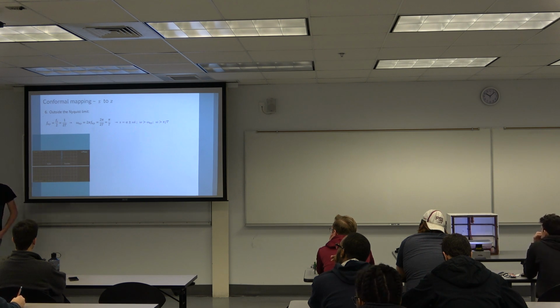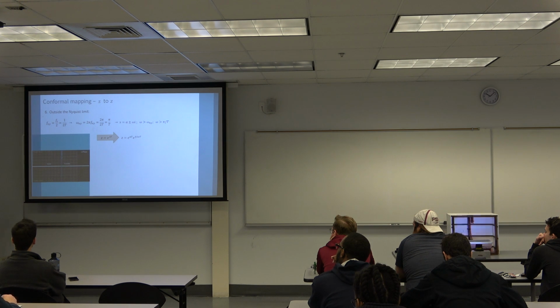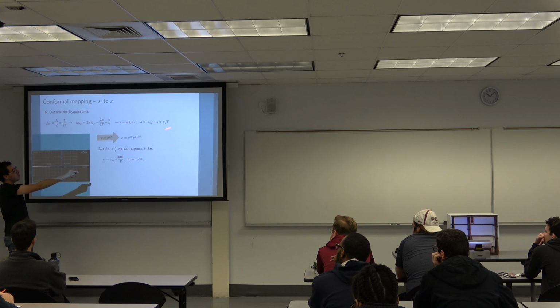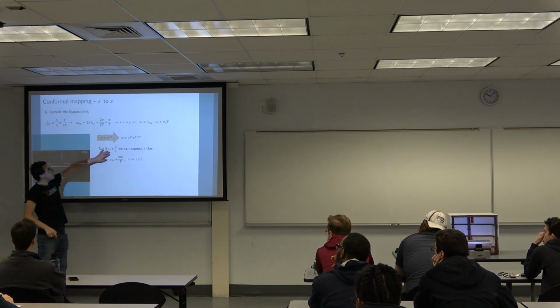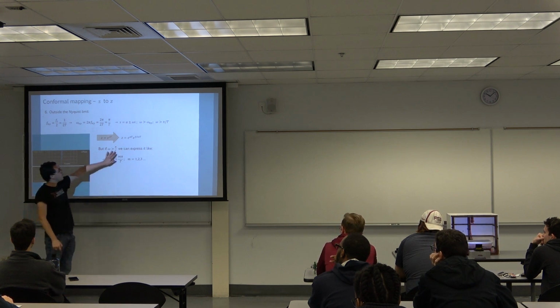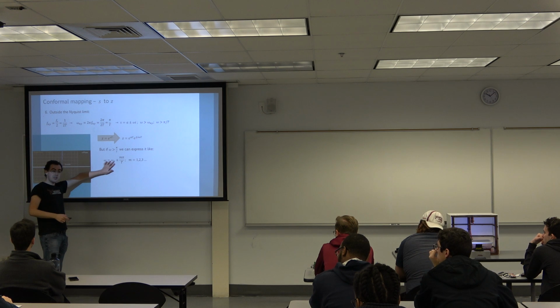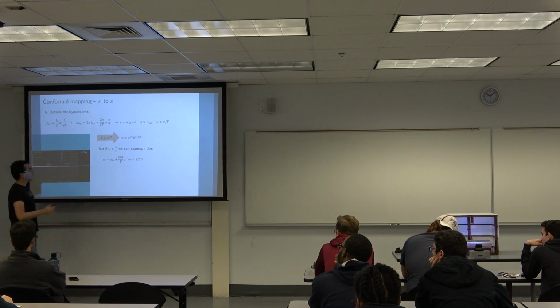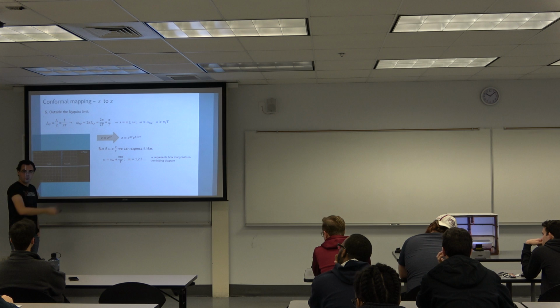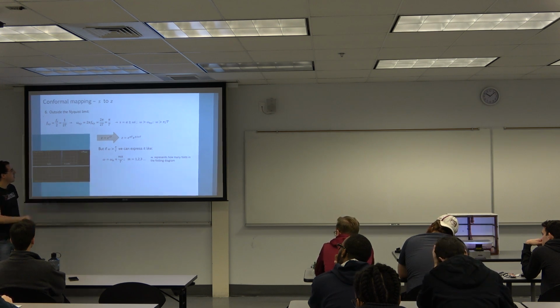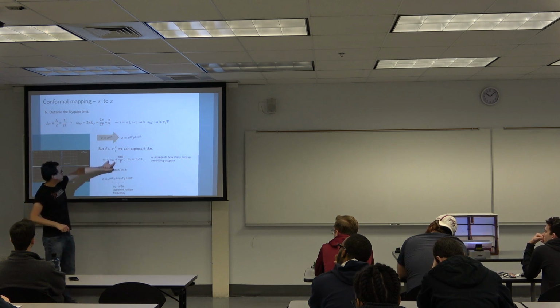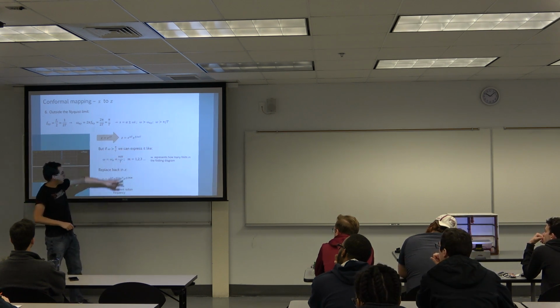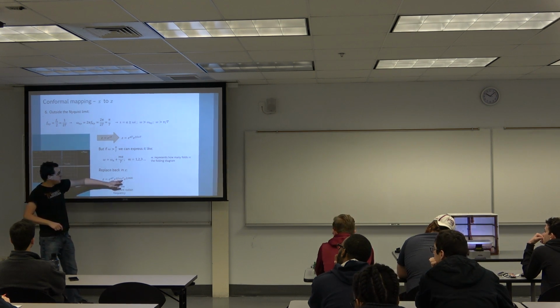where omega is always greater than the Nyquist frequency. And in this case, the Nyquist frequency is pi over T, so this means that omega is always greater than pi over T. If we do that, and we apply the Z transform, then we get e to the i omega T, but omega is always greater than pi over T. So because it's greater than pi over T, I can express it as some apparent frequency omega a, which is less than pi over T, plus some integer number m times pi over T. And m here represents how many folds I have in the folding diagram. So if I do that, I'm just separating the exponential, e to the i omega T, so I get e to the plus or minus i omega a T,